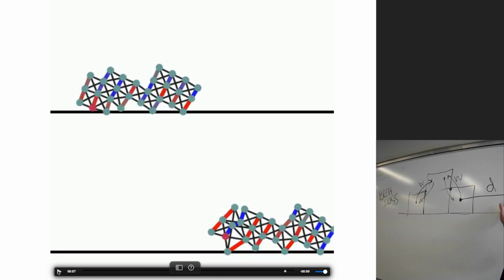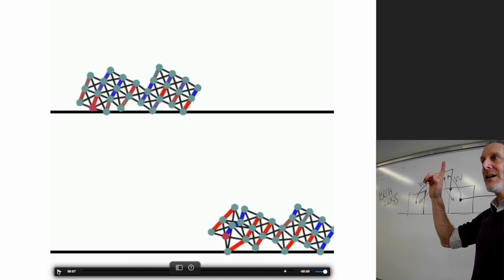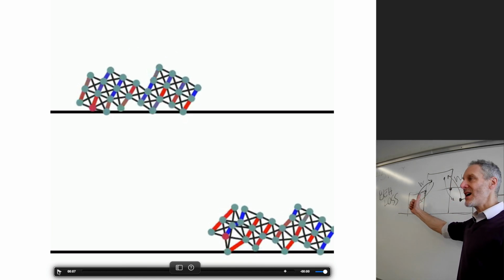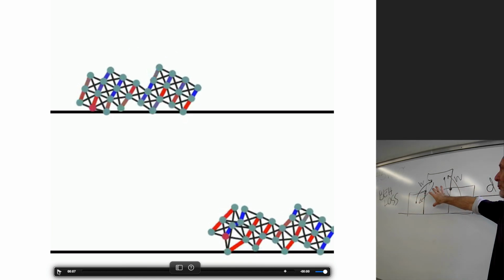The magic of the differentiable physics engine and the magic of backpropagation of error, which has my vote for the greatest invention we've ever come up with, is to now take this error or this loss or this D and start propagating it backwards into the brain and the body of the robot and make changes to the brain and body as we go, so that the next time we run the physics engine forward with a robot with a slightly different body and brain, we are guaranteed, thanks to the differentiable nature of the physics engine, that the next time D is going to be smaller.